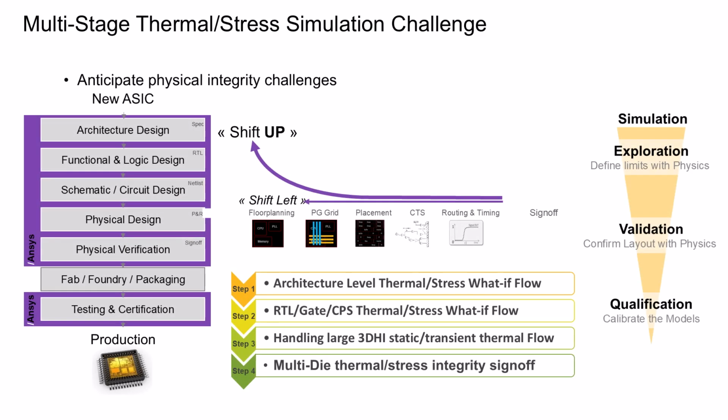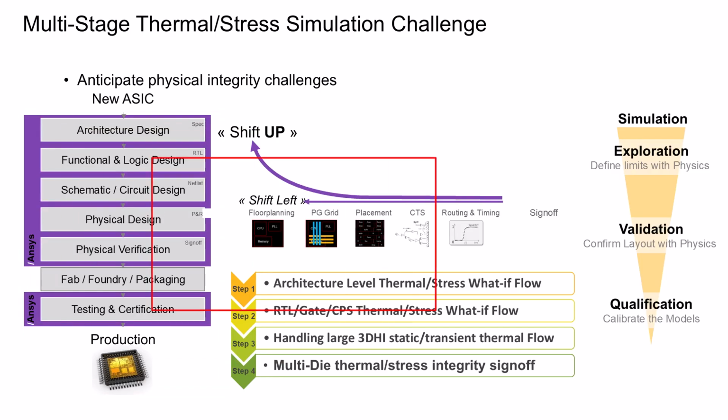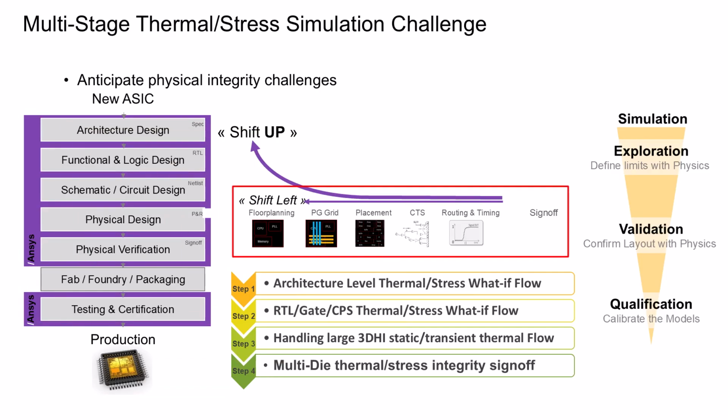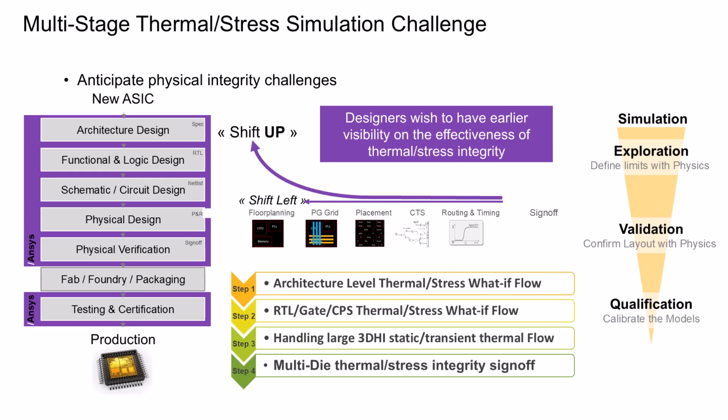So how do we manage thermal and stress risks of multi-die design? The designers should follow a multi-stage co-optimization flow from system planning to tape-out. A shift-left strategy means you have to catch issues early using prototyping models to simulate thermal and structural behavior long before the final sign-off. It is a proactive way to reduce late-stage surprises and costly redesign of the multi-die system, while maintaining all the multiphysics integrity behaviors.